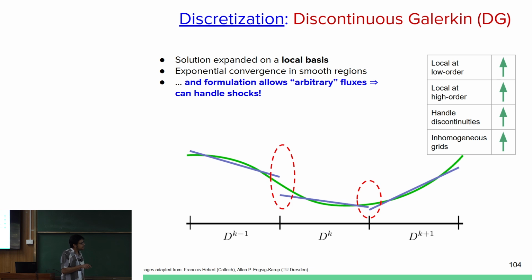It can handle discontinuities as long as discontinuities happen at the boundaries of these cells. Or in other words, as soon as we see a discontinuity forming, we refine our grid and make sure that cell boundaries align with the boundary of shocks, for example. A simple example would be imagine simulating a spherical planet or star with a crust. Your cell boundaries will be at the crust, and new cells will begin in the exterior of the crust and different cells will be in the interior of the crust. As long as the crust is at the boundary of some cell interfaces, we are good.